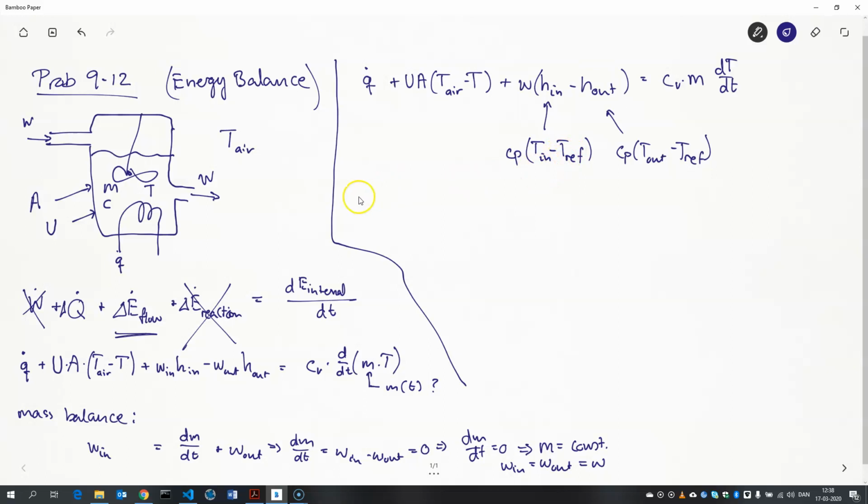So what we get is Q dot plus UA times T air minus T plus W C P times T in minus T out equals C V times M times dT dt.